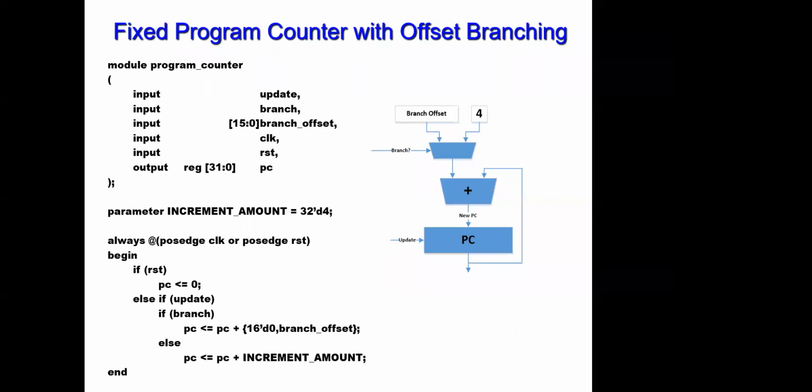We will see also how we can write a simple Verilog program like that if I have a branch offset. Then, of course, this will need to be added plus 4 and so on, and then do the sign extension, like we have already explained, for how we can write the Verilog code. Everything here looks the same as I have described earlier, just adding more inputs.